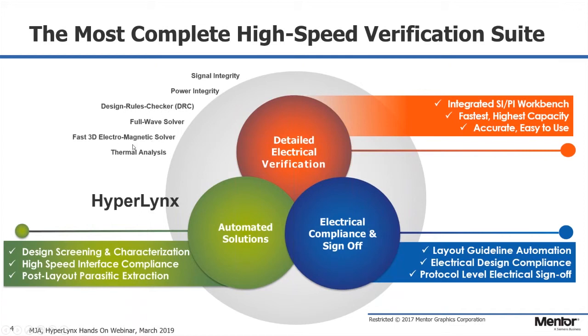And then we've got full wave solvers for your extremely high-speed designs to get accurate via models and other structures for these multi 10s or 20 gigahertz space. And then there's also thermal analysis, again, to help augment that high-speed verification environment.